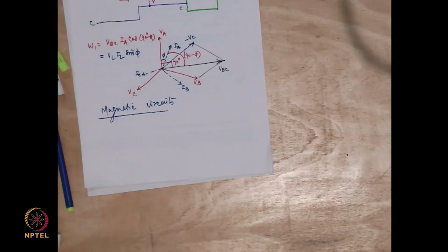So, I am looking at how much torque is produced in the case of a motor, or how much electrical power is produced in the case of a generator. I would be able to say that torque per unit volume will be definitely much higher in a machine made of a ferromagnetic material as compared to the same machine made with wood or a non-magnetic material. So, we are always looking at how a ferromagnetic material behaves when I apply a current,